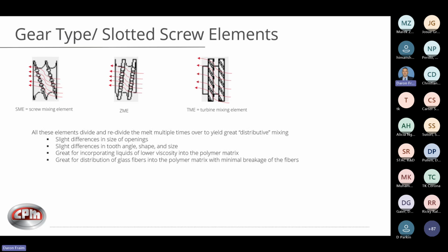So as many of you know, if you're doing glass-filled compounds for mechanical improvement in terms of mechanical strength of the polymer, these are great at really splitting that melt and homogenizing, distributing those glass fibers without physically damaging or reducing the fiber size to retain that mechanical strength.